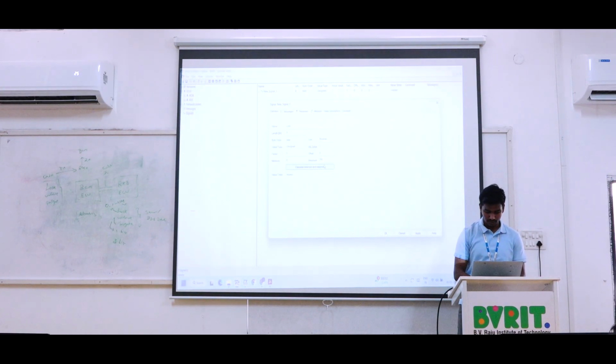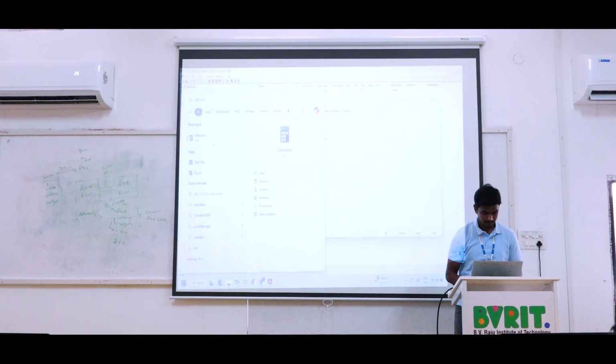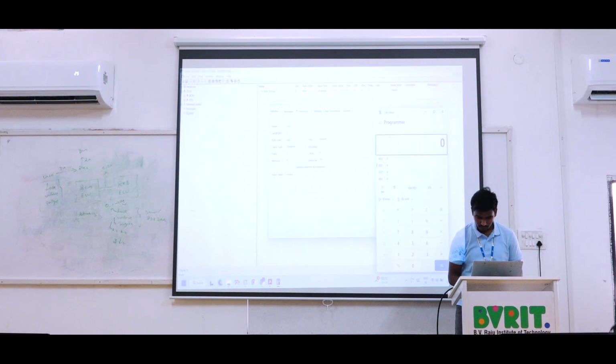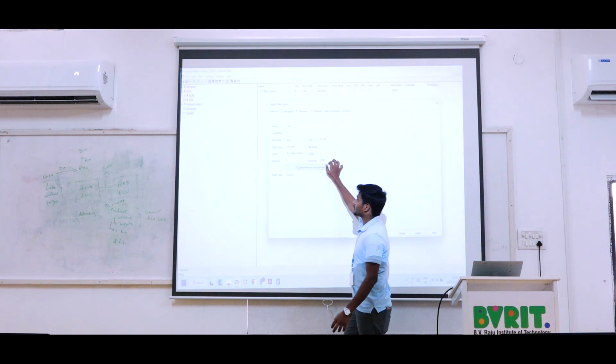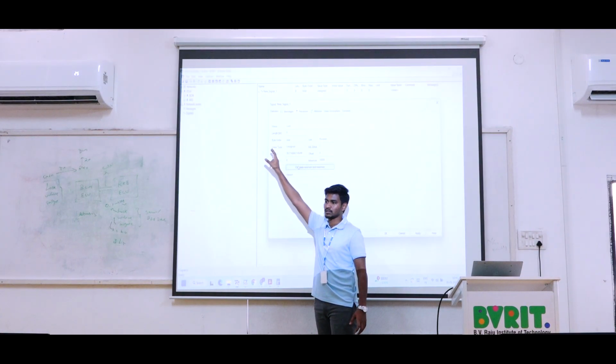So for that we use some calculation: 10,000 RPM divided by the maximum, 255. So we get the 10,000 values, but compressed into the 8 bit range.